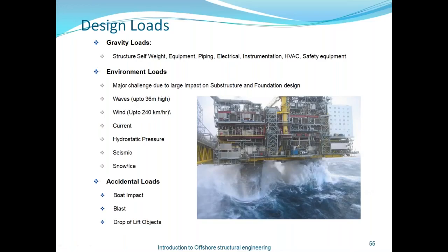It not only cleans, it will try to give the dimensions and the cross section sizes at every half a meter or 100 mm, whatever you decide. Anywhere the intelligent pig says, okay, at this particular section, at this particular length, this cross section is almost at corrosion, that means it is almost to corrode, it will immediately pass its longitude and latitude to the PLC person.